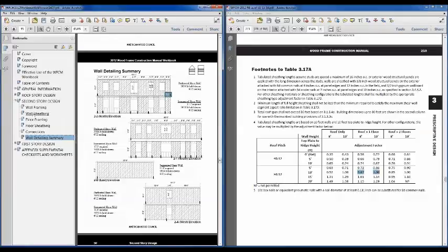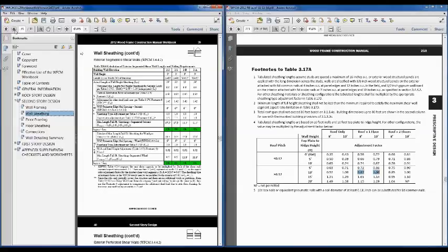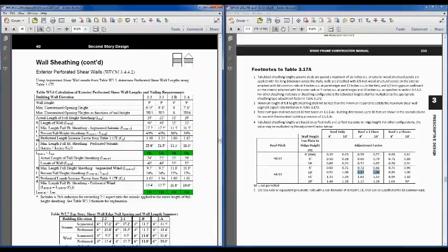So that's what I wanted to show you before we actually jump to the perforated shear wall approach. What are we trying to accomplish now? Back on page 40 with the perforated shear wall approach, we're going to take that segmented approach that we just did, and we're going to use those increase or decrease factors potentially, we'll increase the stiffness of the wall and allow us to move the hold downs to the corners. So that's what this exercise here in the table is about.